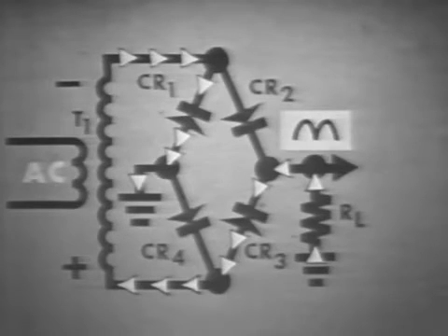From the schematic, we can see that this narrows the trouble down to the 4 diodes, one of the 4 diodes, or perhaps one of the common connecting wires to the diodes. Well, the diodes are the most likely source of failure, so we could check each of them for an open. With only half-wave output, then, look for an open diode as the most likely source of the trouble, or perhaps one of the connecting wires might be open.